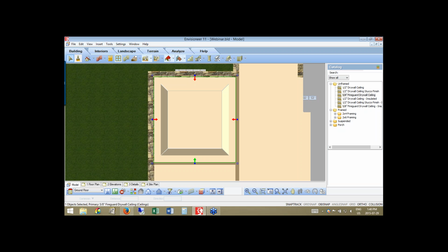Those arrows hold information about the style of the ceiling on that particular side, because every side of the ceiling can have different properties. You can see that on the side where I have the green arrow, it's got a 1-foot skirt width. And then it goes up on a 45-degree angle to the new height of the tray at the top. What if on this particular side we didn't want it to have a skirt? We wanted it to be 0 right up against the wall. This will allow us to change that.